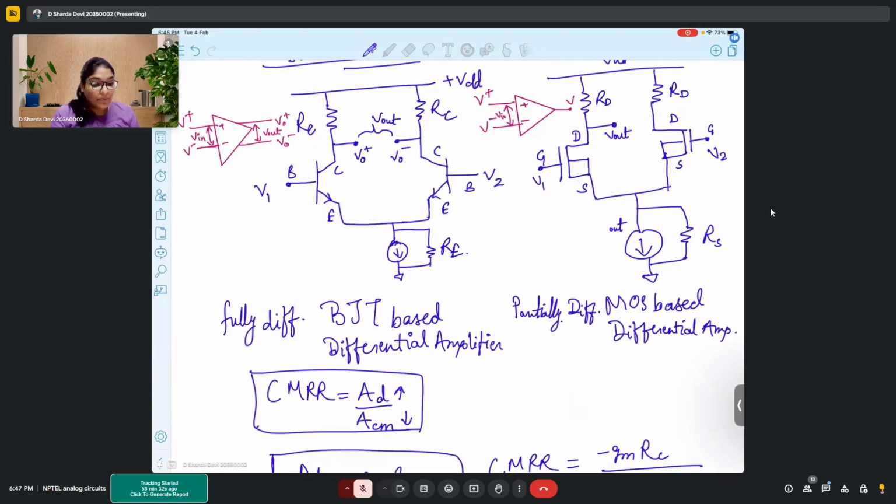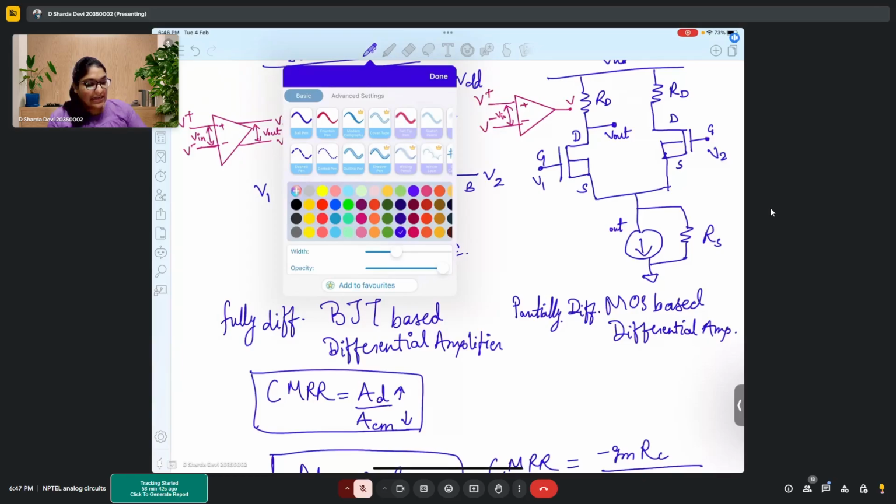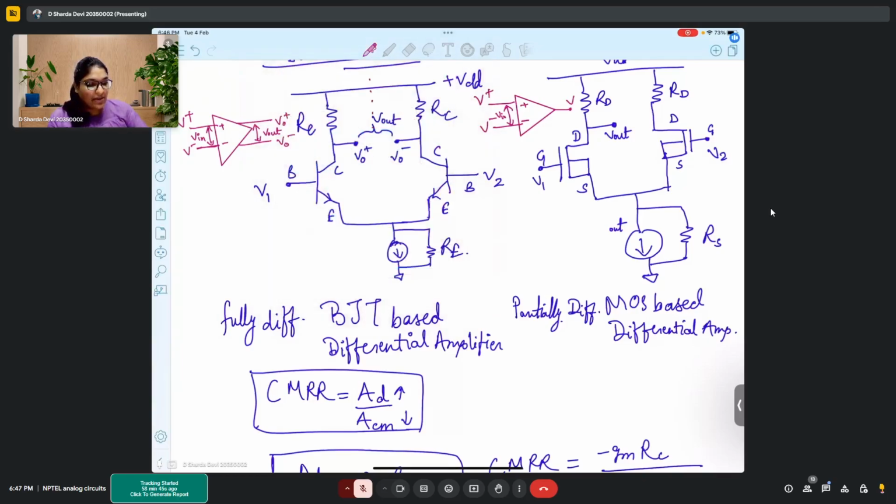For common mode, basically what happens is, when you are designing a differential amplifier, if you see the two stages that I have drawn, I have drawn them exactly the same. So this is a symmetric circuit, basically. A differential amplifier is a symmetric circuit. The idea is both branches present in your differential amplifier are matched, so the transistors have the same values and behavior, as well as the resistors and all the circuit elements used in both branches.